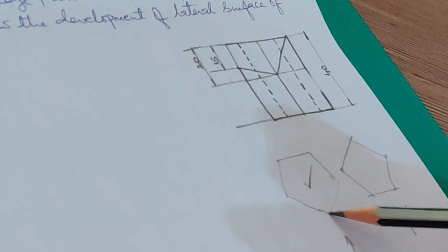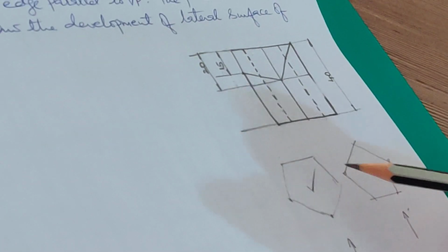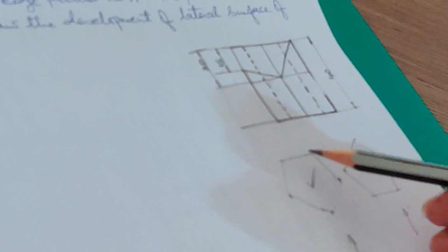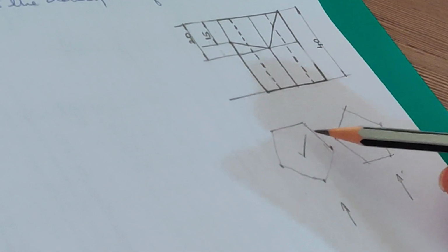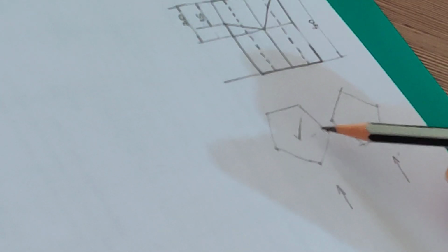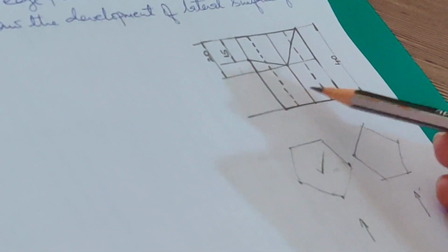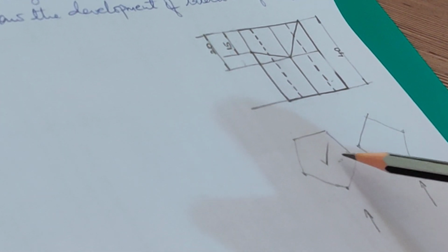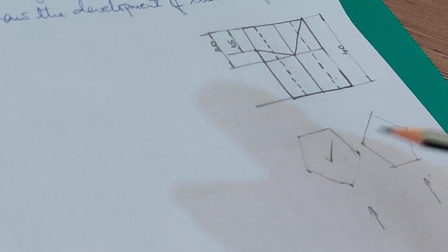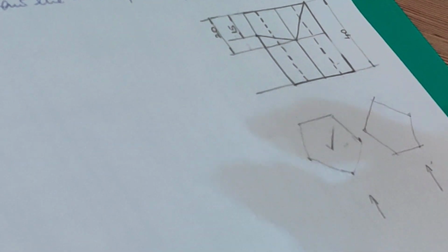So when you look from here, this is visible, this is visible, this is also visible. But these two are invisible as they are away from the observer. So you should draw a pentagon with this position. So this is very important to know because you are not given the top view. You are just given the front view, these two lines, these two edges have been made dotted. So this is the position of the pentagon I should start with. Okay, I'll erase this now.